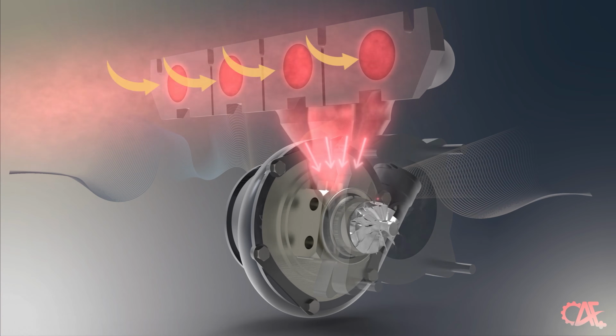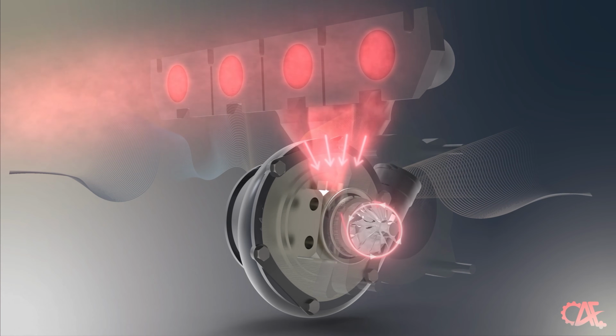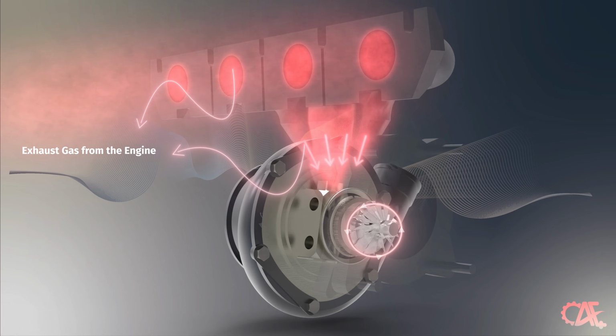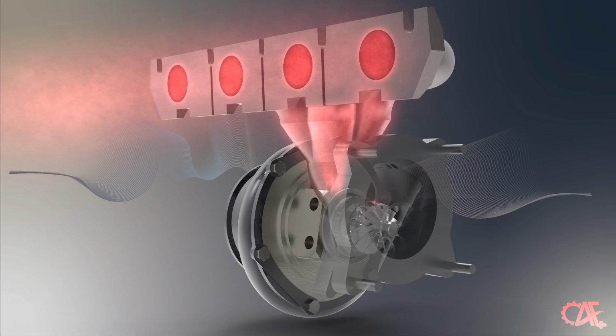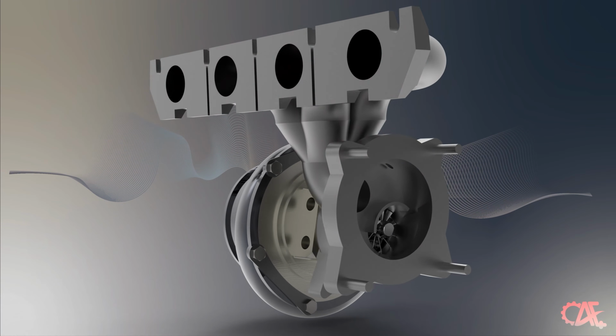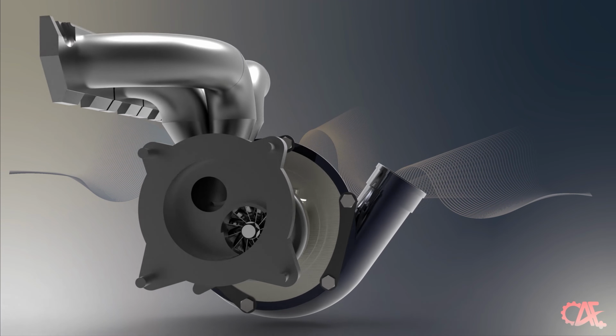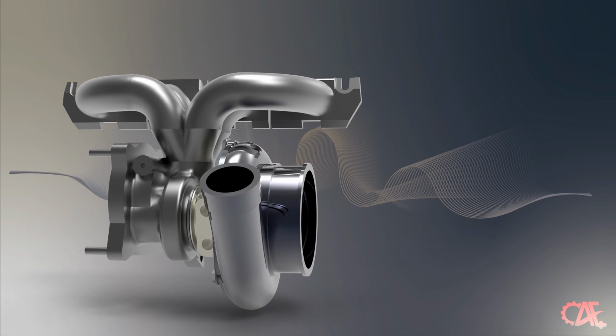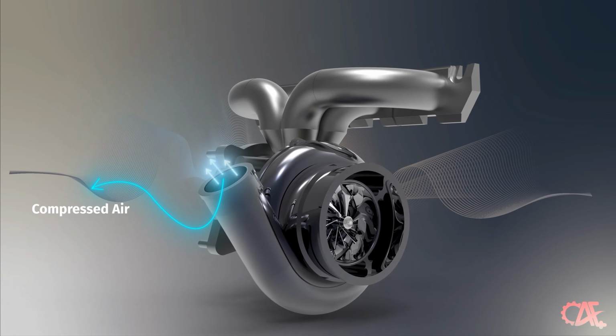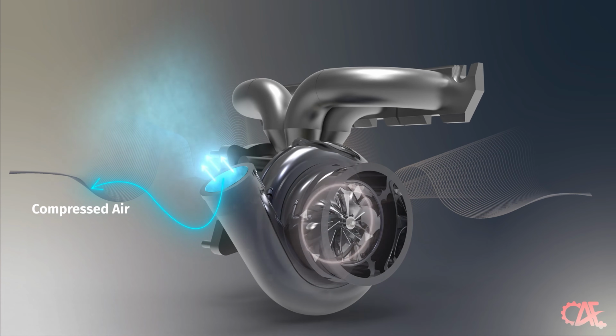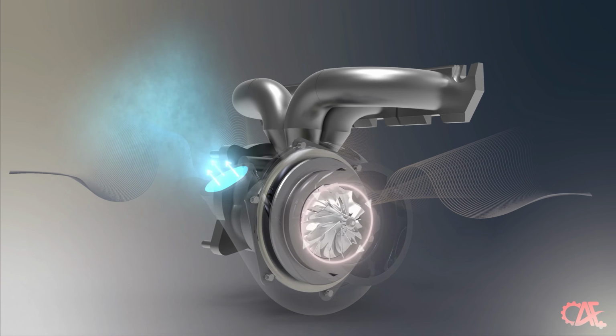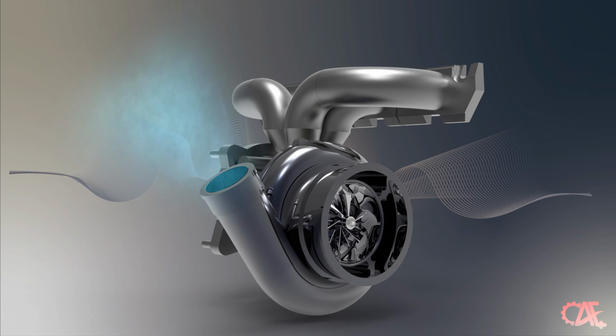A turbocharger in an internal combustion engine is essentially a device that harnesses the energy of exhaust gases to compress the intake air. As illustrated in the animation, the exhaust gas, indicated by red arrows, drives a turbine which in turn rotates a compressor shaft. This compressor then feeds compressed air, shown with blue arrows, into the engine. This compression significantly increases the volume of air entering the engine, thereby boosting the engine's power output for its size.